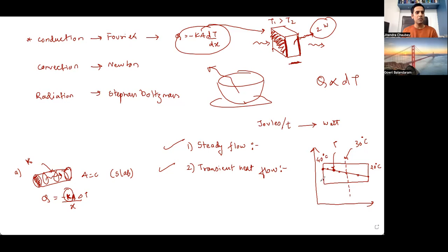You can make the temperature a function of length. Like this is x equal to 0, here it is x equal to L, and over here it will be some x equal to x1. Temperature respectively over here would be T0, over here some T1, and over here TL. The linear interpolation is basically a ratio of slope. Slope is a ratio of differences.